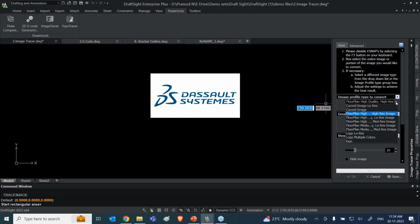If you can see over here, once I drop down, I have different options that are available. These are the kernels upon which the image tracer is going to be working. Whenever a designer is working, what kind of data he's trying to extract from the image can be defined over here. Whenever you're working on a floor plan, if you want to extract data from a floor plan image into a CAD editable entity, you can select the floor plan. Whenever you are trying to extract data from a logo, you can go for the logo option.